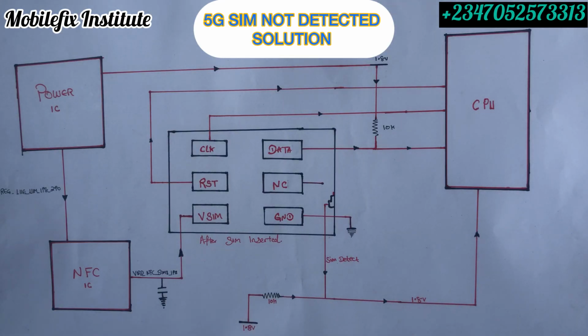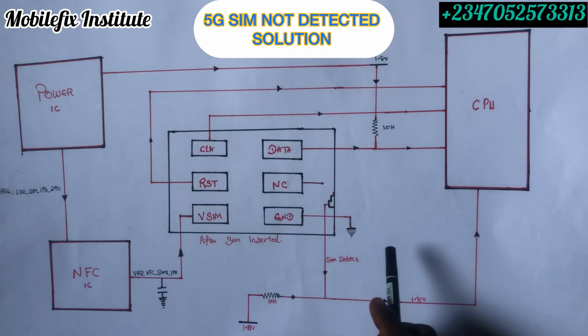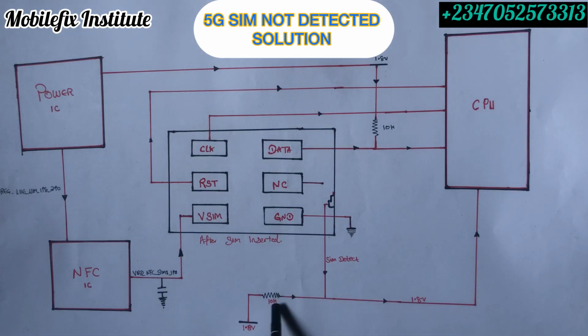You follow this line and trace, or you can jumper 1.8, because this line is connected to different lines and different circuits. So you can tap 1.8 that is still connected with this same line from another source, and then bring it to this resistor if it is open. So you can give 1.8 to this resistor. Now after testing it, if you discover that there is 1.8 volts on this side of the resistor, and you test the other side, it will not give you voltage. Why? Because you have not inserted your SIM card. It is only when you insert your SIM card that the voltage will pass.